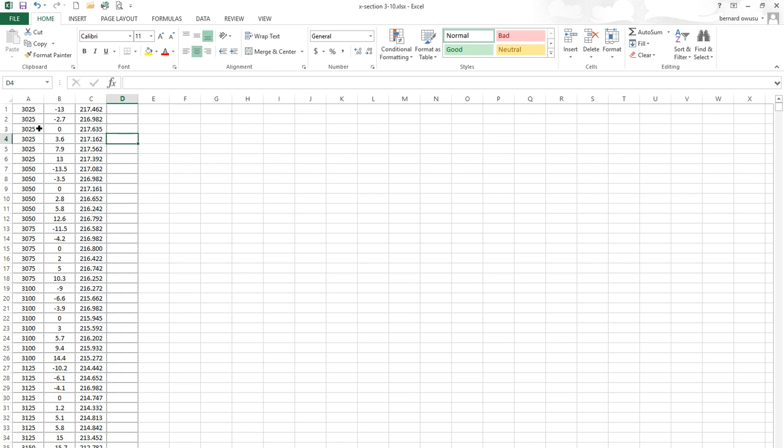Very good. Now, before we can bring it into AutoCAD Civil 3D, there are some modifications, about 2 or 3, depending on the data you have. The first thing you have to note is that there should be no plus. Normally changes you may write maybe 3 or 1 plus something. It should be a full number. If it is change 0, just put 0. If it is 0 plus 100, it should be 100, not 0 plus 100. So we have to go through this data and be sure that there is no plus sign. If not, it will not see it as a number or as a change, but like an alphabet or something. So let's go through it and see.